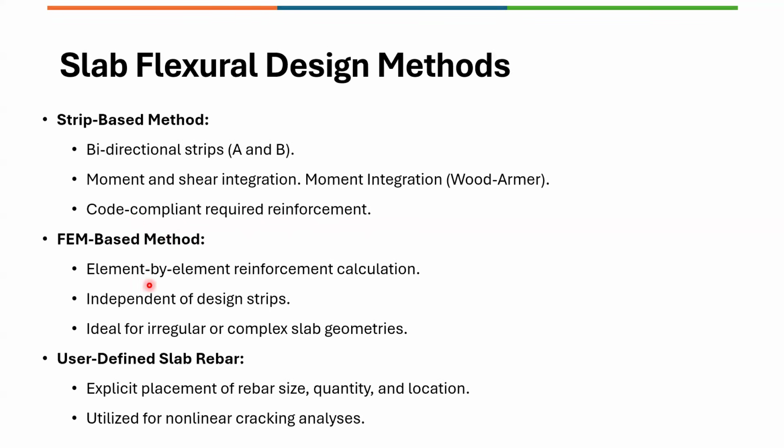selected for the design. So FEM based is available, which is given in situations where the strips cannot be drawn because of the slab geometry, irregular or complex. Then you can utilize the FEM method. So this is independent of the design strips. So you get two outputs whenever you draw the design strips for designing the slabs. You'll also get the FEM based output.